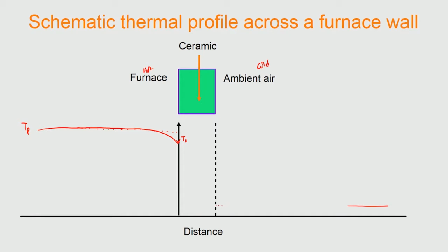If you note down the T infinity, which is the far away temperature, the outer wall would have a temperature slightly higher, and asymptotically this is how the profile should look. Ti minus T infinity is the temperature difference over which the heat transfer takes place from the outer wall of the ceramic brick. Between these two, if you assume that steady state heat flow is taking place in 1D, then you could join them. Okay. So, this is how the temperature profile would look.